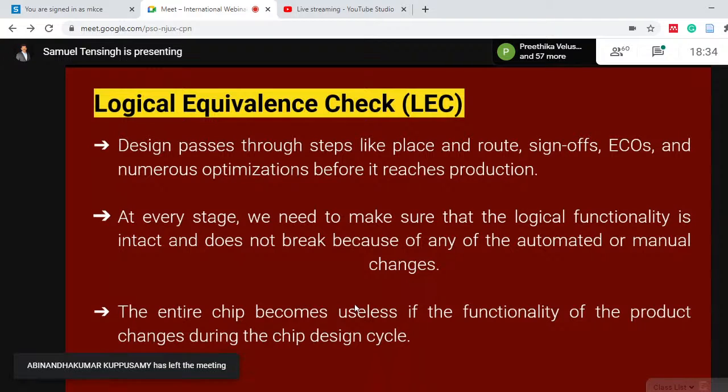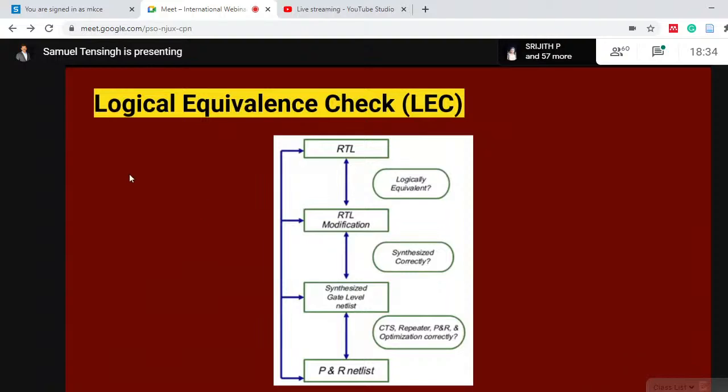All these are the basics of physical verification, but in industry we will have a lot more checks, like antenna checks, and also the crosstalk violations. All these are additional checks, and also we have perk checks, and also many other checks are being implemented now. But these are the basics of physical verification.